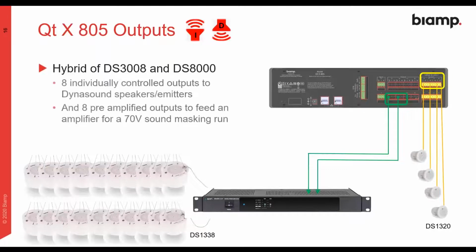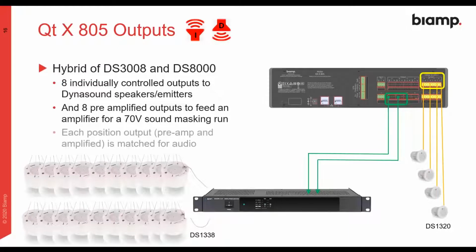We're recommending that, since they can't be broken away from the amplified outputs, in planning, if you use a pair of outputs for line level, keep those line level and don't share across. You could in theory share it, but then you're sharing any EQ adjustments that you might do across both types. So you might have a difference in speaker type that's out there on the 70-volt system, but this would give you the option to build in a full system and then support some existing pre-infrastructure devices that are in place, and then route whatever you need to it.